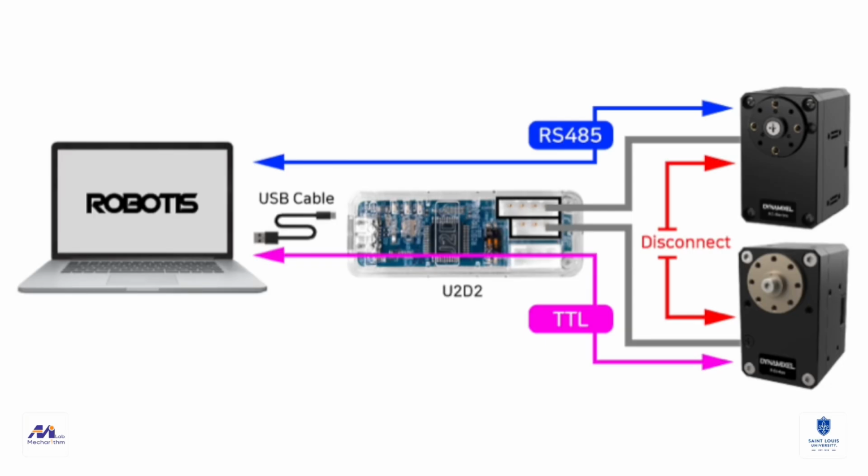As we learned in class activity 1, Dynamixel is a brand of smart servos commonly used in robotics and mechatronics projects. The communication with these servos is typically done through serial communication using a USB to serial adapter. The device files with ttyDXL in their names are created when the adapter is connected to the system and represent the virtual serial ports associated with the adapter.